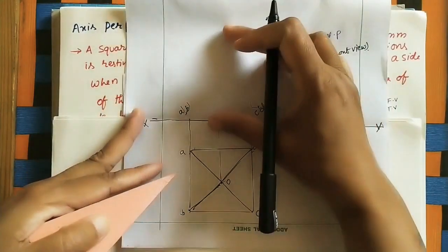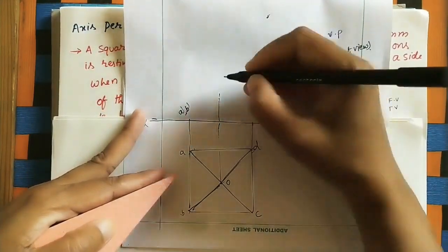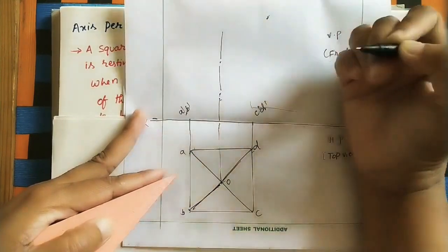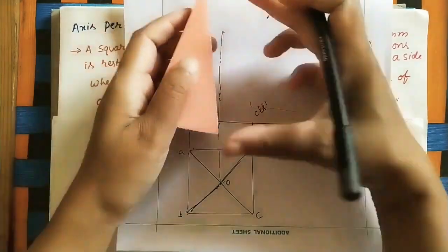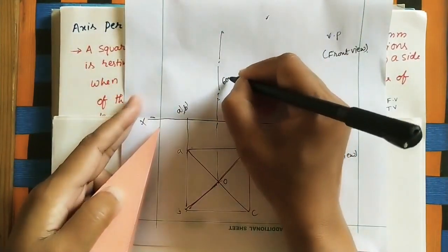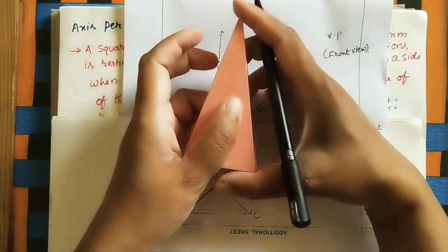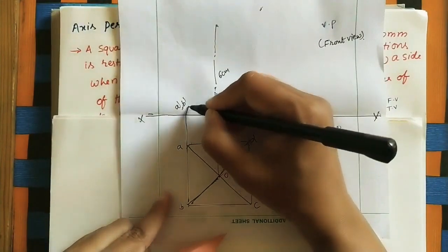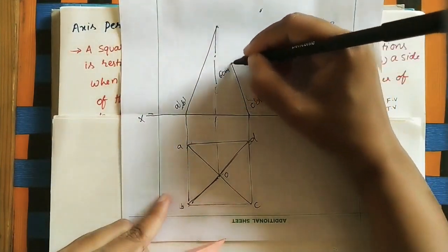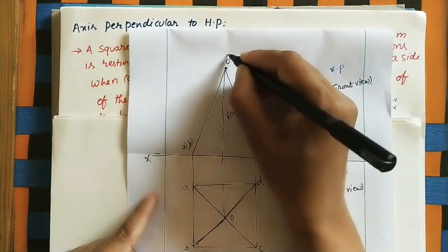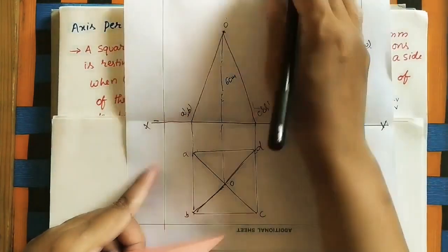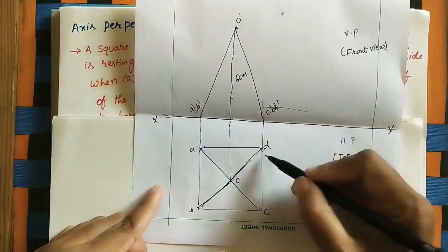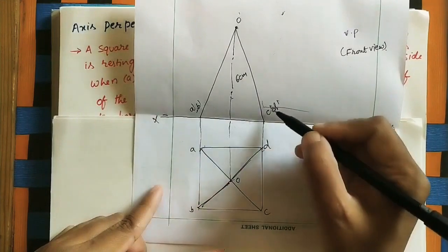So for taking the height here, first do the axis line. Axis is always two big lines with a dot. Okay, two big lines with a dot like this. So how much height is it from this? Total is 6 centimeters. So take 6 centimeters height for the axis, and we can see the slant edges in the front view. Okay, so join using a scale this and this with the apex. Give the name O dash for the apex. In the top view we are giving O, for the front view we are giving O dash. Here also for the top view we are giving small letters, for the front view we are giving dash: A dash, B dash, C dash, D dash, like that.